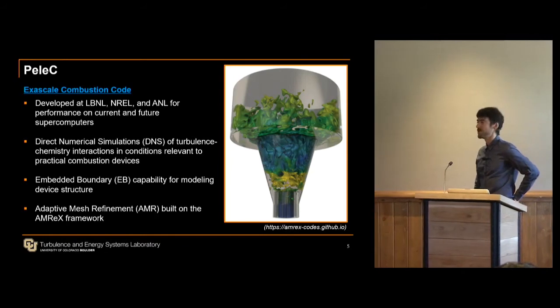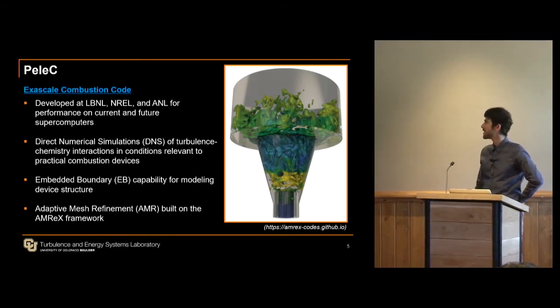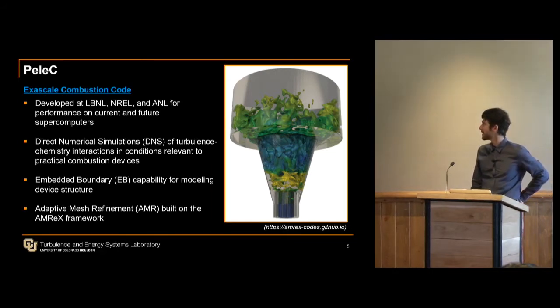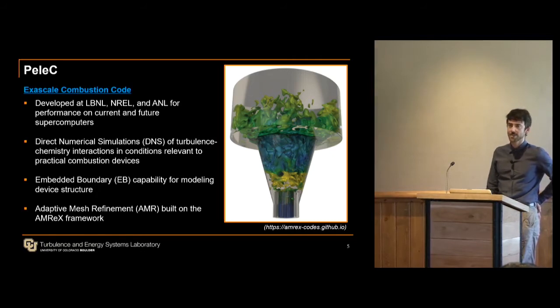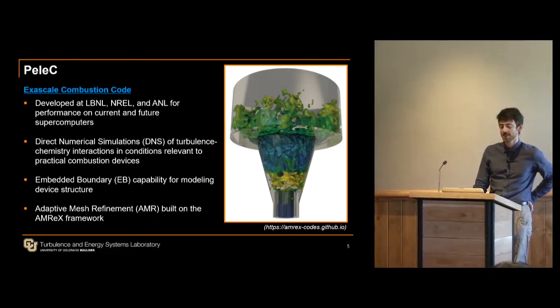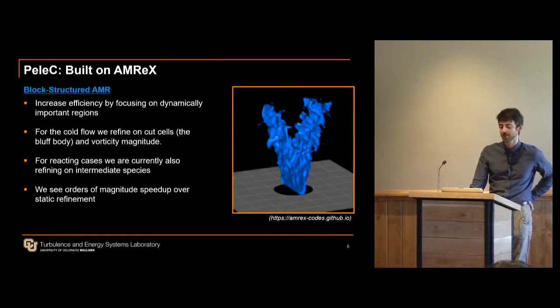So about our computational code, as I mentioned, we're using PeleC. This is under active development at AMReX in Colorado, right near us at the University of Boulder, as well as Lawrence Berkeley and a bit at Argonne as well. The intent here is to do direct numerical simulations of turbulence chemistry interactions, and it has device modeling capabilities through the embedded boundary framework. That's a cut cell approach in the finite volume mathematics that are used. This code also uses adaptive meshing to provide localized refinement.